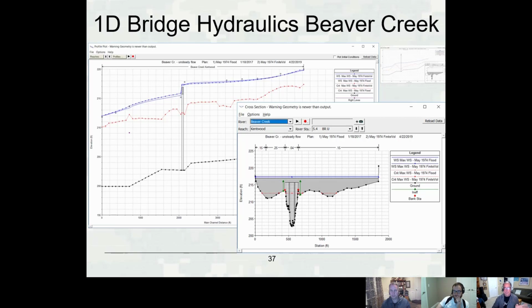The second thing, though, is that whether you realize it or not, in 1D finite difference the equations are developed for the main channel, and then the overbanks are combined into what's called a floodplain. If you go into chapter 2 of the hydraulic reference manual and look at the 1D finite difference solution, the equations show 2 compartments: a channel compartment and a floodplain compartment. That floodplain compartment is a combining of the left and right overbank into one thing. So there's really only 2 flow areas in the 1D finite difference for a cross section, channel and floodplain. Floodplains are combined.